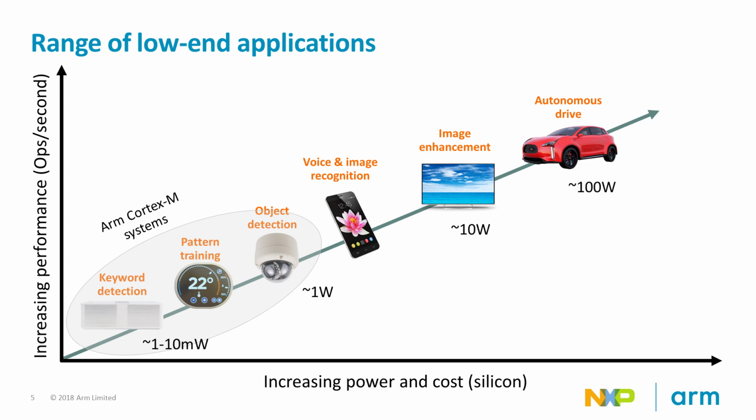Let's look at the type of applications that are in reach of a Cortex-M based system. Typical use cases are keyword detection for a voice-based human-machine interface. Also, object detection using visual or other sensor data, like ultrasonic, is a common case that a Cortex-M processor can deal with. When looking at the popular software frameworks for machine learning, like TensorFlow, Caffe, Theano, and others, it becomes clear that these can impossibly be operated on even the largest microcontroller. The amount of resources and compute power required is magnitudes beyond what is available on an MCU system.